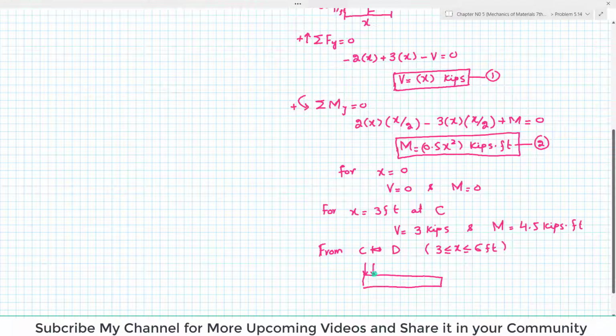The upper 2 kips per feet will be there over the length of 3 feet. So it is 2 kips per feet, and this length is 3 feet, and below you have a distributed load of 3 kips per feet. We have taken an arbitrary distance x, and x is greater than or equal to 3 and less than or equal to 6 feet. So this distance is 3 feet. When you cut the beam, there will be a shear force and a reaction moment. Let this point be J.